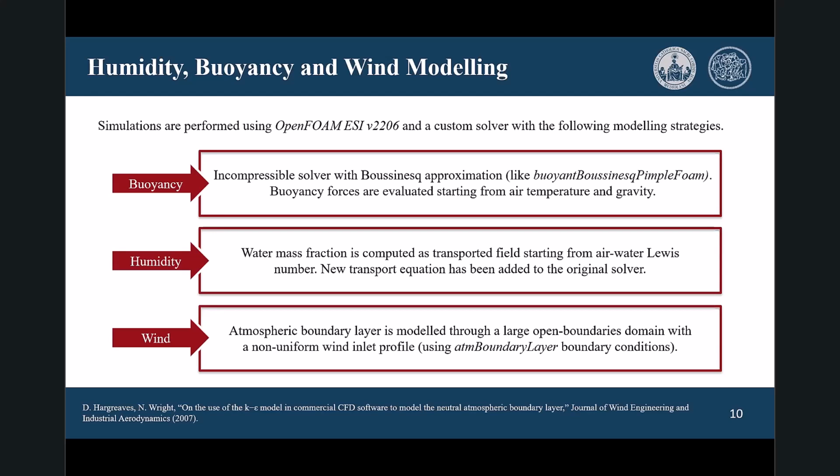In addition, as we want to consider wind-induced ventilation, we need to consider the atmospheric boundary layer. And we are using the atmospheric boundary layer family of boundary conditions from OpenFOAM.